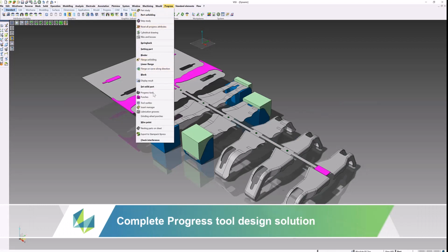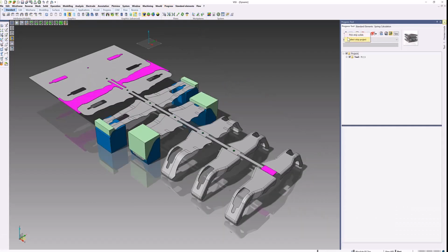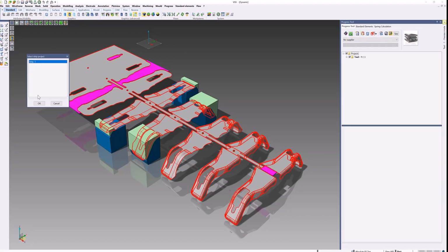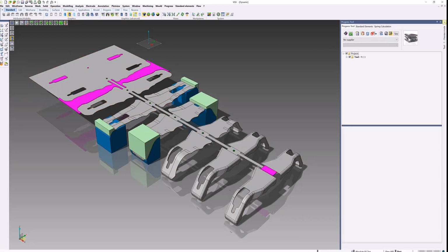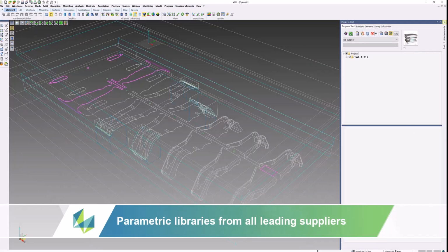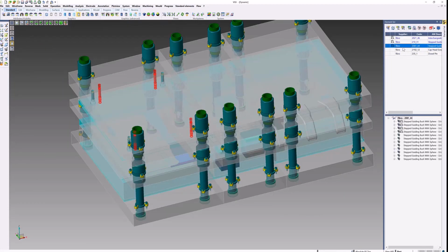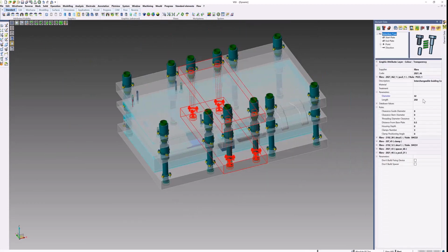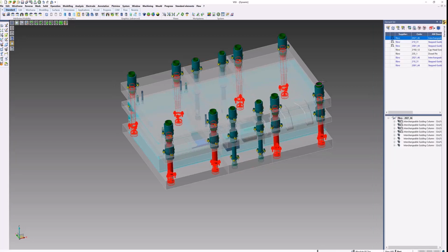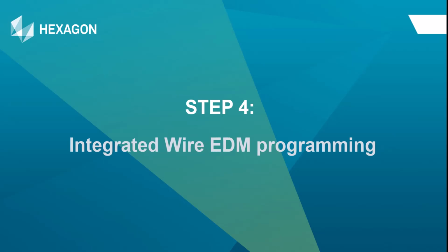Most stamping dies have several standard components, including die plates, shoes, die sets, guide pins, bushings, heel blocks, heel plates, screws, dowels, and keys. VISI supports standard parts libraries from all leading progressive die tooling components suppliers and cloud-based services. The proprietary parametric component library enables both quick and accurate placement of each standard component and ensures that modifications can be made at any stage during the project.